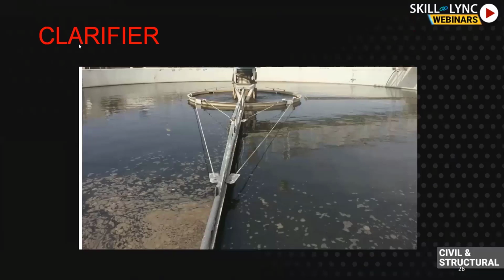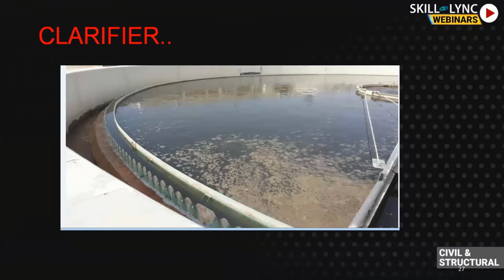This is again where interdisciplinary coordination will come. All the sewage water from the clarifier, which has come and been scrubbed from there, will move out down in the conical section, and the clean water will go from the weirs to the next secondary or tertiary process. So you will need to know what type of weir you need and clarifiers.